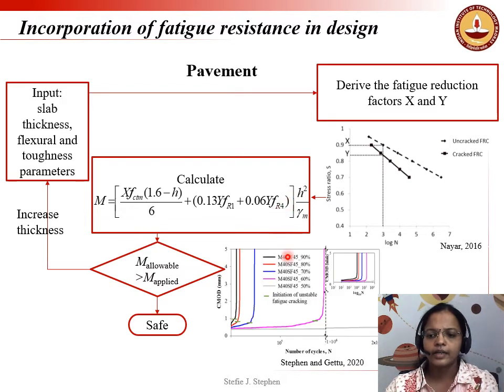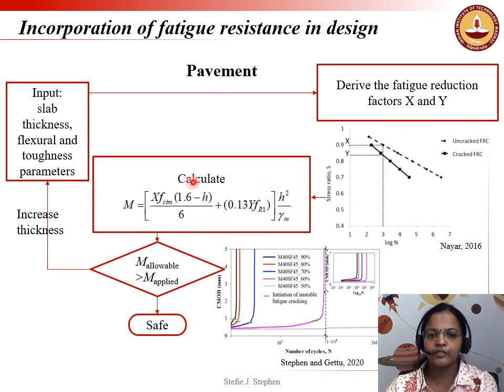However, previous research findings say that an element with crack openings of more than 2 mm will fail suddenly under fatigue loading. Since FR4 is the residual strength at a crack opening of 3.5 mm, it has to be considered as 0 in the design equation. So the equation has been further modified like this and it will be used in the design.